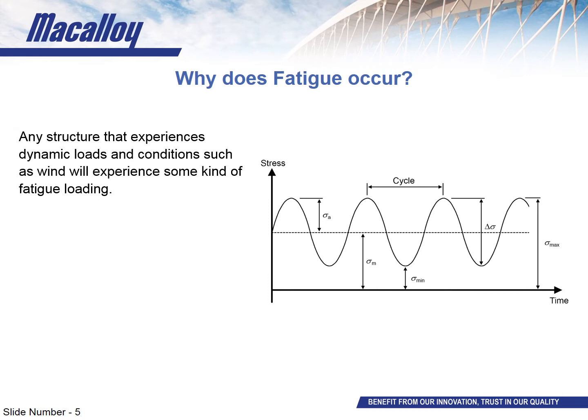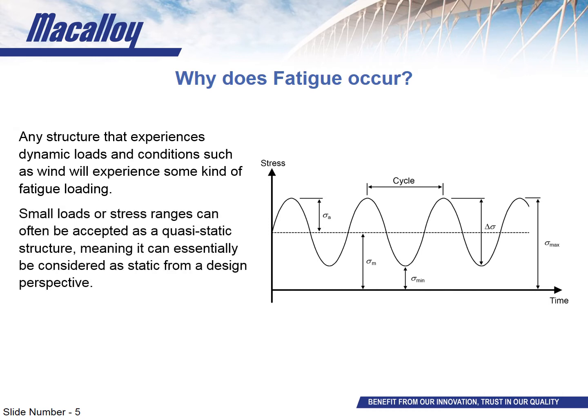Now, a lot of structures do actually experience a small amount of fatigue as a result of loading such as wind, for example. However, if the load itself, or the change in loads, is relatively small, the loading conditions can be considered what's known as quasi-static. Now, quasi-static basically means that from a design perspective, you can consider it to be essentially static.